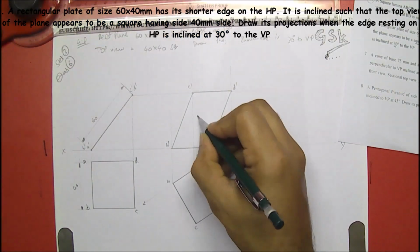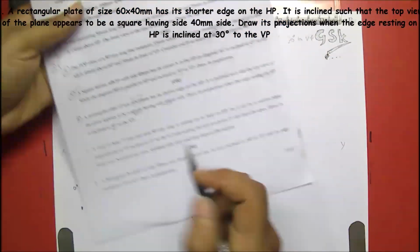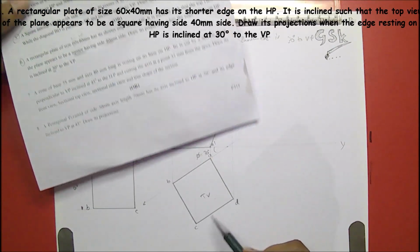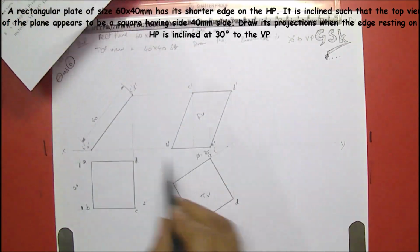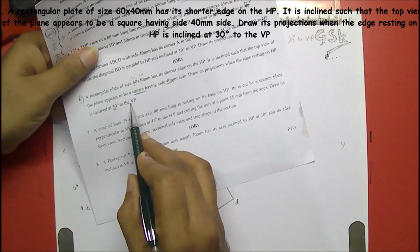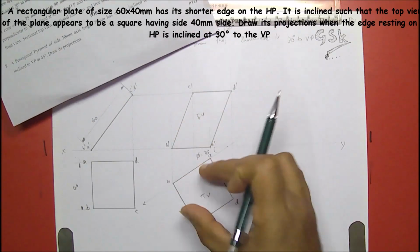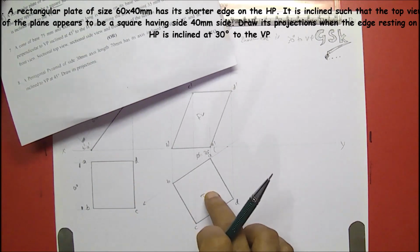Right, this is the front view, this is the top view. Already it is given that the top view of this rectangular plate appears as a square. Here this is the square of 40, it is satisfied. Next, draw the projections when the edge resting, means this A dash and B dash, is inclined at 30 degrees to the VP. See here, this is 30 degrees to the VP. So in this position we have to draw the front view and top view. Top view is a square, it is already given, so we have reproduced it here.